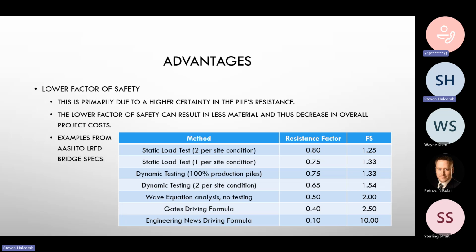Do you normally do this? The person doing the PDA, is it normally the owner bringing somebody in, or does that typically work with the contractor? That's a really good question. For DOT, we've taken it where we want the PDA contractor working for us, just because we want them to help us and brainstorm, but I think it's more common in the lower 48 for the contractor to hire the PDA to work just for them, and you just put in the contract, do PDA testing, give us the thumbs up.